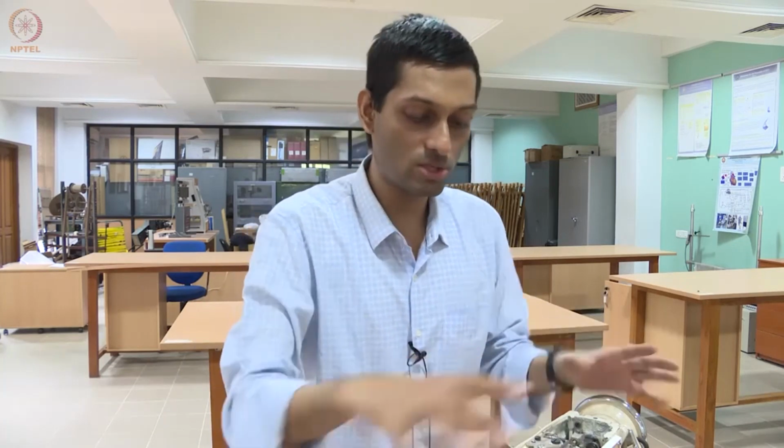So when you look at machinery, how do you break it down? We are looking at primitives. This entire mechanism, when you look at it for the first time, might look overwhelming. So the way to approach any complicated machinery is to break it into what we call primitives. You look at it from the standpoint of a crank slider. Any mechanism will always have a rotary input. Typically we'll have back and forth motion, or some other oscillatory motion. We'll have a lever that rocks. So you'll have various different kinds of motion.